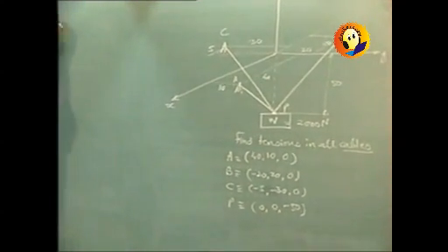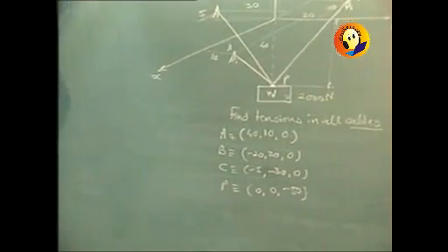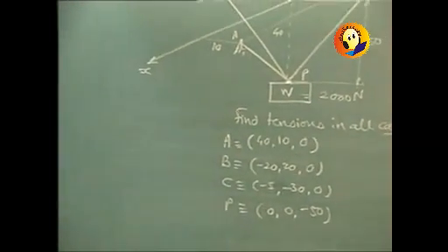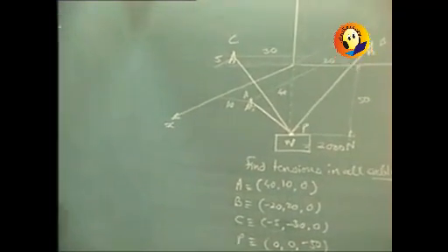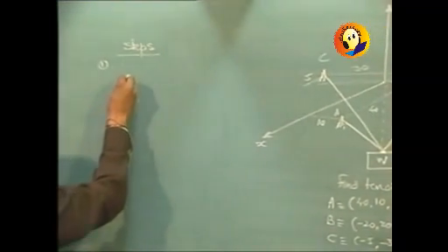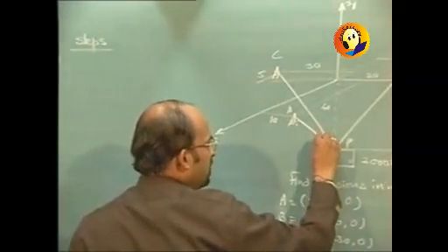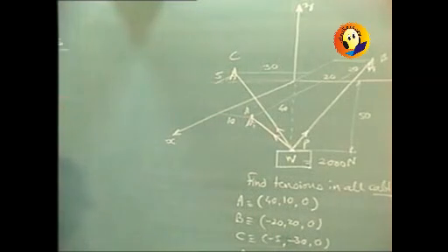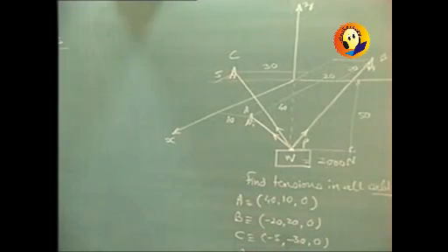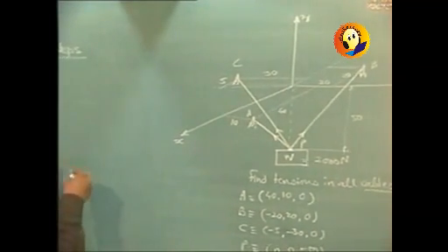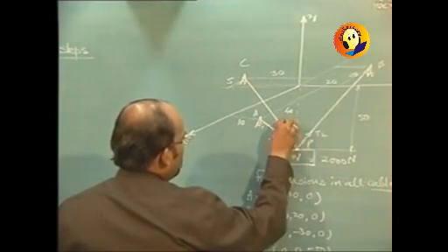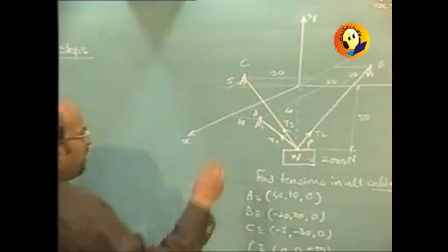Now the procedure or the steps for solving the problem, one by one I am telling you. First step is to find out, because now the weight will be supported by the tensions which are acting in this manner. Weight will be supported by the tensions which are acting from P towards A, towards B and towards C. So let us assume the tensions to be T1, T2 and T3 respectively, PA bar, PB bar and PC bar.